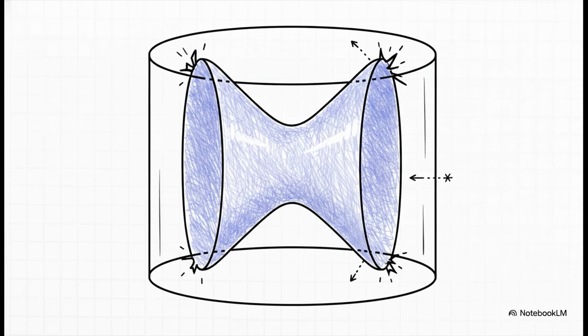And this brilliantly illustrates the difference between 2D and 3D geometric controls. Because it's a 3D tolerance, cylindricity creates one single tolerance zone bounded by two perfectly concentric cylinders for the entire surface simultaneously. Unlike our circularity slices where the center points could kind of drift around, cylindricity forces the entire length of the surface into one rigid 3D jacket. It locks both the circular elements and the longitudinal elements together. If your part is barreled, wasted, or tapered, even if it's perfectly round at every individual slice, it will absolutely crash through those two concentric 3D boundary cylinders and fail inspection.